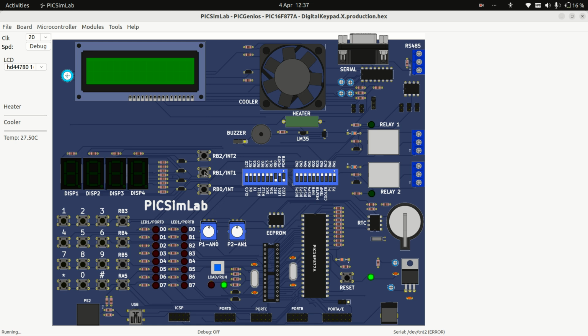It's off. Do the same thing for RB0, RB1: press, release. Press the switch. See here, still it is on. Again you need to press, then it will turn off. This is what state change is. Here the LED is not toggling; it toggles during level detection.